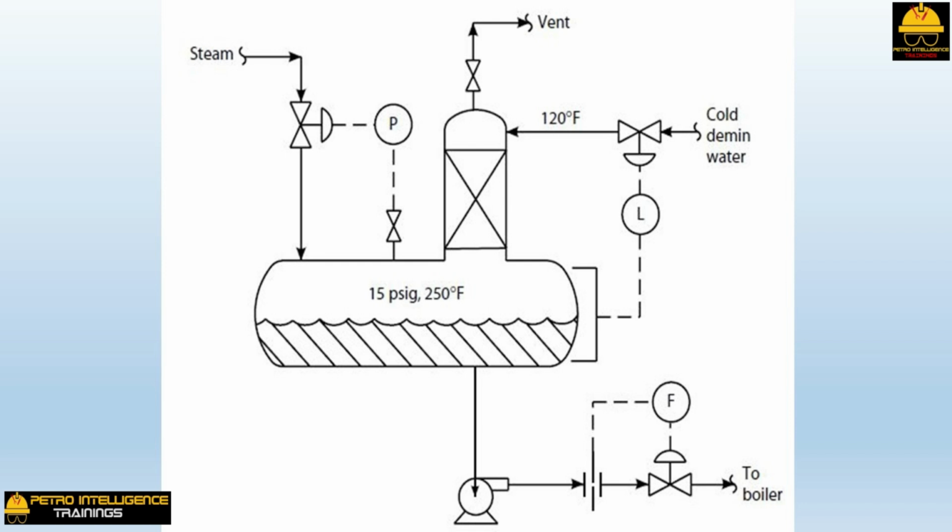This vented steam is being used to strip out the residual O2 in the cold water feed. Note that there is sometimes a second, hotter feed to the deaerator, in addition to the cold water feed to the stripping section. This secondary feed is steam condensate, which, having already been steamed, bypasses the stripping section. The exception to this generalization is steam condensate recovered from turbine exhaust vacuum surface condensers. Such condensate may have been in contact with air that has been drawn into the surface condenser shell and thus may have to be deaerated again.